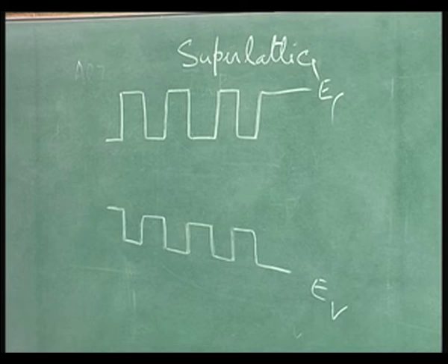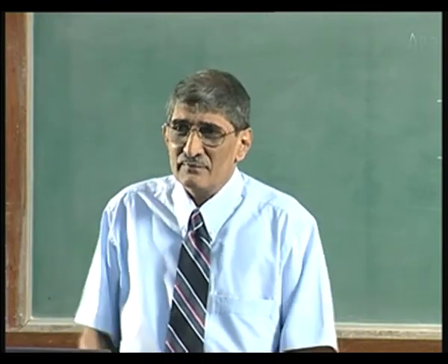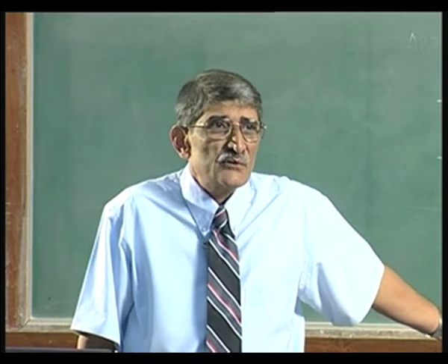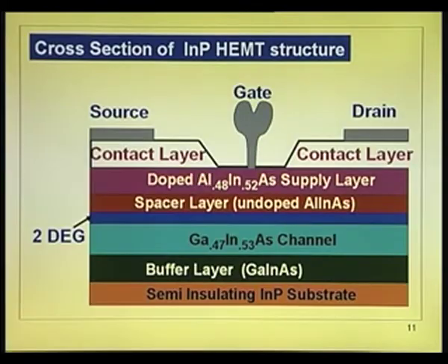It is that type of structure. I just deliberately brought it to you because do not be flabbergasted if somebody comes out and uses the term superlattice. It is nothing but a heterostructure, a number of heterostructures which are present there. Okay, so that is the most interesting part of that particular thing. So, this is a layer which is just protecting this channel layer from the contaminants, defects, etc., present in the lower layer.